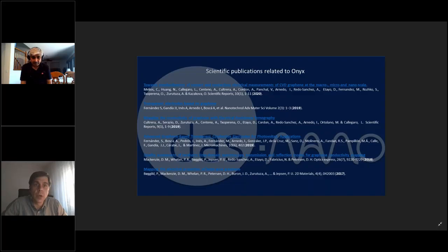Van der Pauw only gives you a number for the full wafer. What we have done in collaboration with INRIM is a tomography Van der Pauw, so you make a lot of Van der Pauw measurements and extract them. This is a contact method, but a very well-known method, as you know. And the results with the terahertz signal are very comparable. They are in very good agreement.